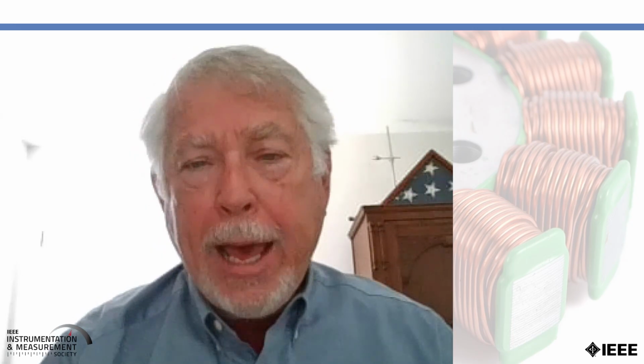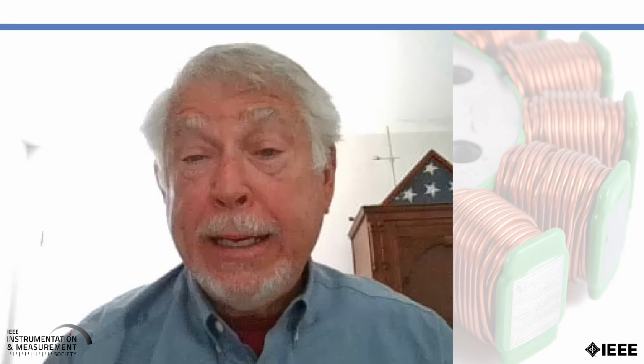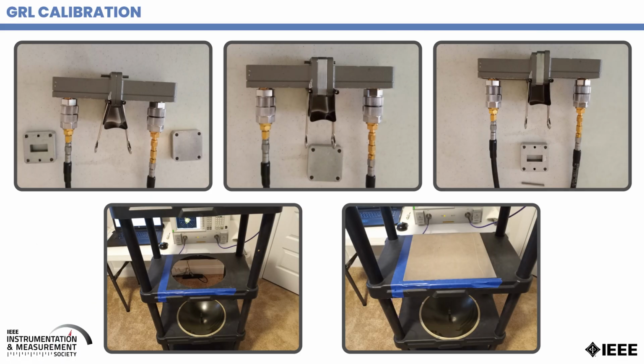To do a GRL calibration on this fixture, we're going to do a calibration at the end of the coax that are used to connect to the antennas. We'll do a TRL calibration here. After that is performed, we'll do the GRL calibration by measuring the empty fixture and the fixture with the plate of metal placed between the antennas.